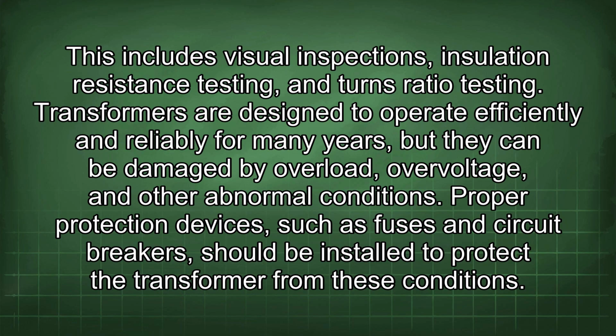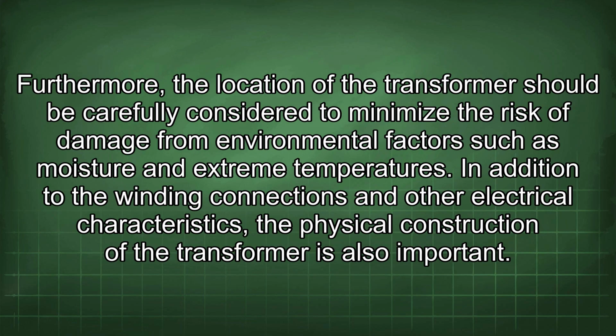Transformers are designed to operate efficiently and reliably for many years, but they can be damaged by overload, overvoltage, and other abnormal conditions. Proper protection devices such as fuses and circuit breakers should be installed to protect the transformer from these conditions. Furthermore, the location of the transformer should be carefully considered to minimize the risk of damage from environmental factors such as moisture and extreme temperatures.